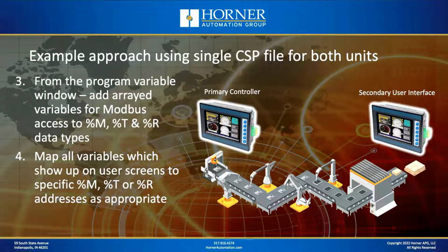What we're going to do there is add a set of arrayed variables: one set for M bits, another set for T bits, and another set for R bits. Remember, M's are retentive bits internal, T's are non-retentive bits internal, and R's are internal retentive word type variables.